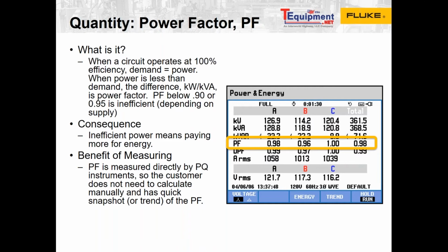And to measure real power, you also need a meter that can simultaneously measure voltage, current, and all the stuff mentioned before that lies in between over a 1-second period. It's a guide, it's a standard for all power quality measurements. It's got to happen over a 1-second period. And a digital multimeter can't really do that.